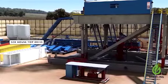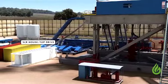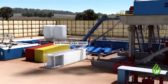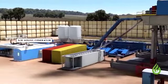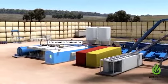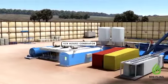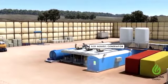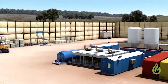SCR house top drive, an electrical housing unit which balances and controls the energy used to power the top drive. SCR house generator, an electrical housing unit in close proximity to the generator which balances and controls the energy used to power the rig site, also called a breaker house.